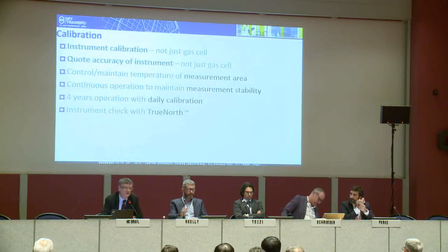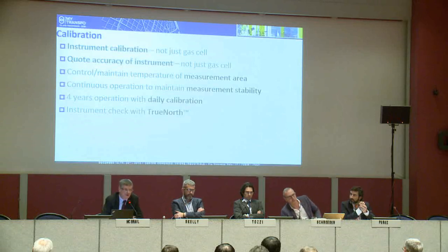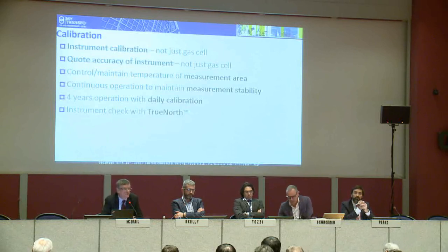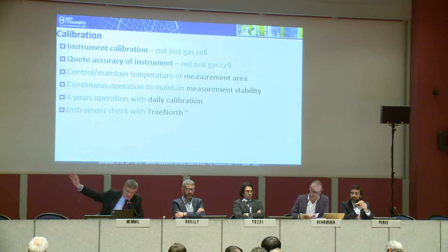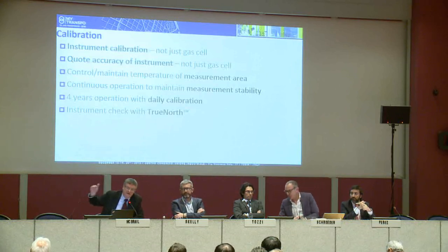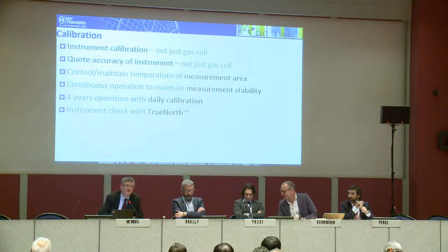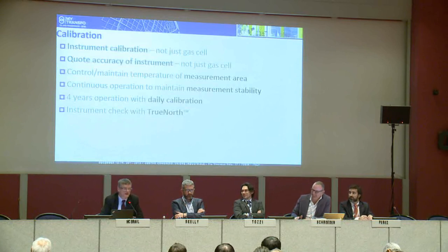It causes drift in the whole measurement system. To go with that, we don't just keep the temperature of the cell where the measurement is made controlled. We control the whole environment. So we're plus or minus 1 to 0.5 of a degree. This means that the measurements are consistent. I want a result so that when I don't get 200 parts of acetylene, I get 1, I can trust the result. That to me is what I'm going to spend the money for.